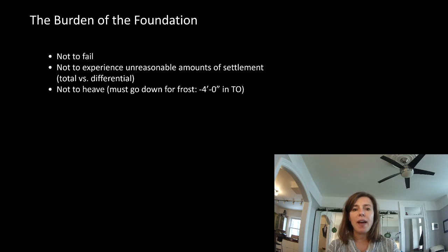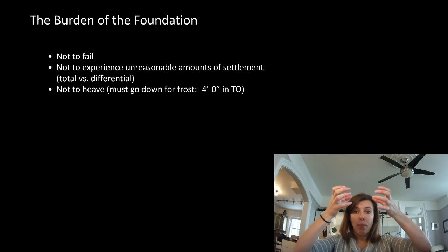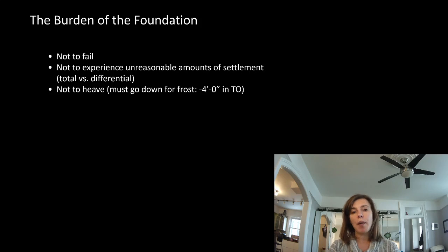Seems far-fetched to imagine that, but if you've ever seen fence posts that are popped up out of the ground, what's happening there is frost heave. So what we do is we make sure our foundations are down far enough that ice or water, when it freezes, can't be underneath the foundations. It doesn't mean that there's not water there, but the cold air above can only penetrate so far down into the ground. And in southern Ontario, that's 4 feet.